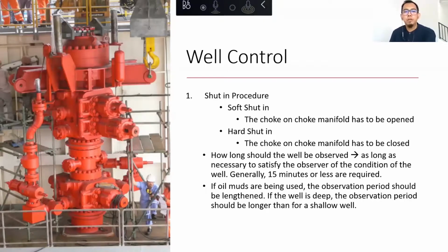Because if oil mud is being used, the observation needs to be lengthened, because there's a potentially longer time for the system to get to its equilibrium state, where the gas that is dissolved inside the oil-based mud is released before it's fully in equilibrium.